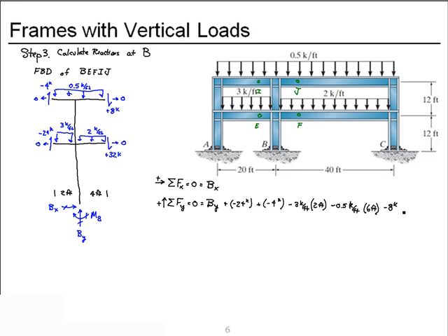The 8 kip downward load at J. The minus 32 kips. And we run out of room on the end, but don't forget the 2 kip per foot acting over 4 feet right next to point F. Put all those together, we get By is a positive 85 kips in the direction drawn.